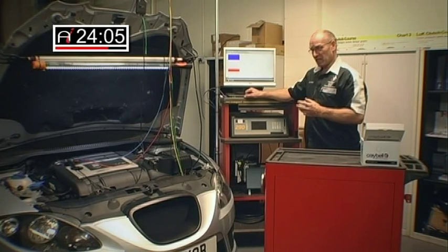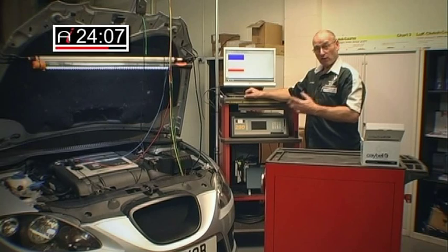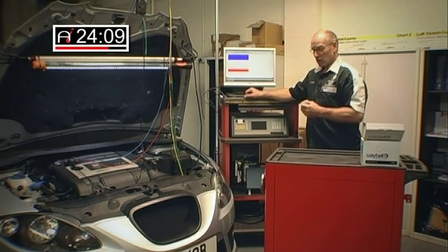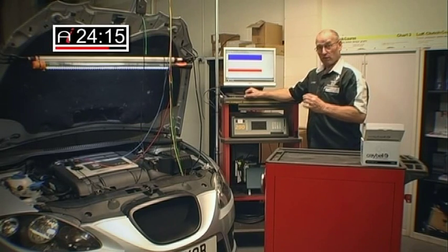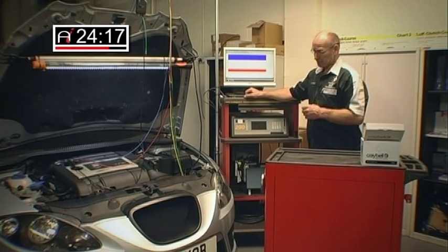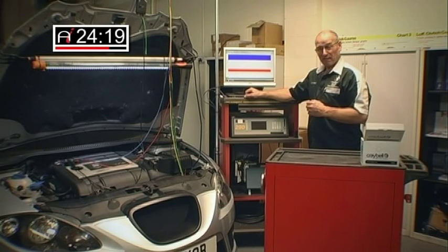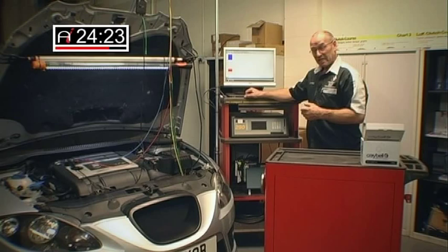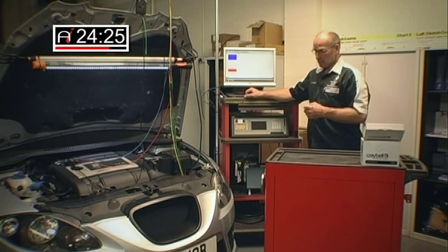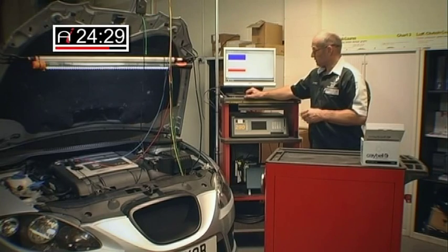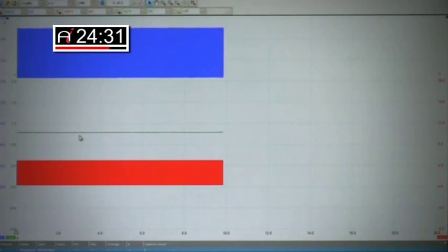What I'm suggesting is, irrespective of the volume of an engine or the performance of an engine, we are getting very similar figures. And 1 volt at idle, 100 milliamps, is a very consistent value. So we're having some confidence in interpreting this as a means of testing air mass across an entire range of engine systems. So what we're looking at there in green is current.